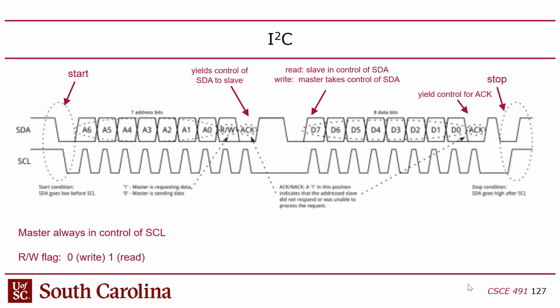Okay, now for this lab, you're going to be writing C code in the Arduino IDE that performs the master functionality, and the slave will be performed by the sensor, right? So you're going to be writing code that talks to the sensor using this language, the protocol. As the master, you're going to have to toggle the clock up and down, up, down, up, down, right? And then you'll have to change the data in some cases and read the data in other cases, so that data is both an input and an output pin. Make sense?